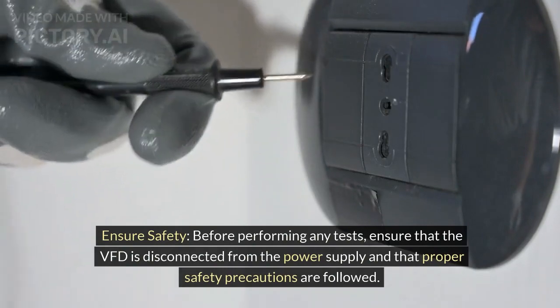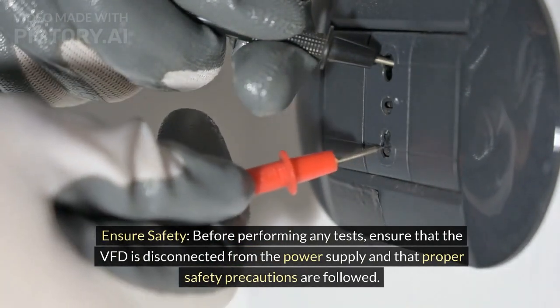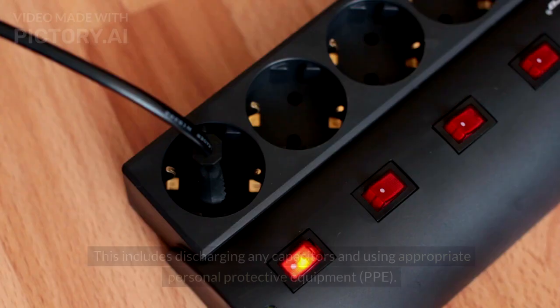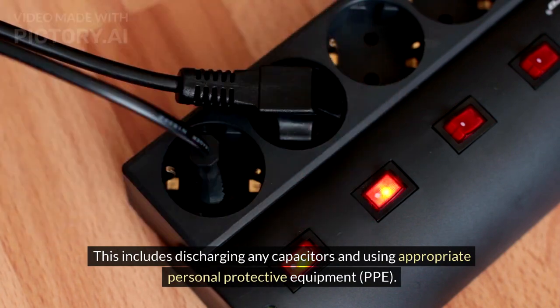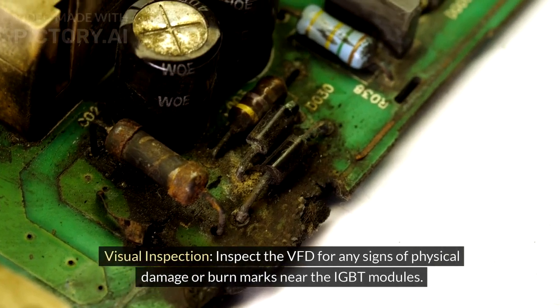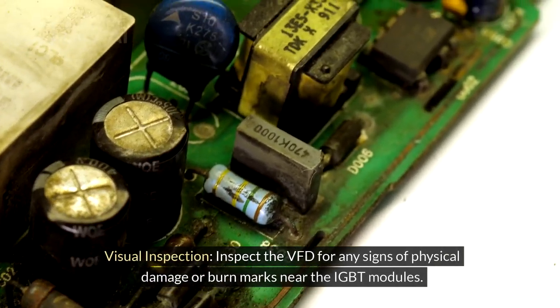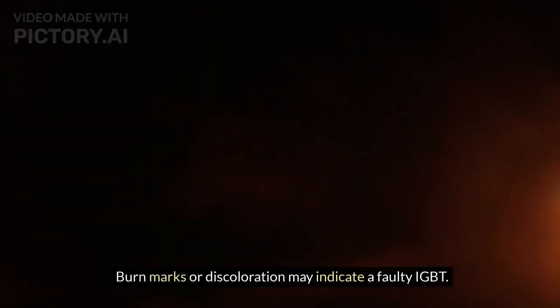Ensure safety. Before performing any tests, ensure that the VFD is disconnected from the power supply and that proper safety precautions are followed. This includes discharging any capacitors and using appropriate personal protective equipment, PPE. Visual inspection. Inspect the VFD for any signs of physical damage or burn marks near the IGBT modules. Burn marks or discoloration may indicate a faulty IGBT.